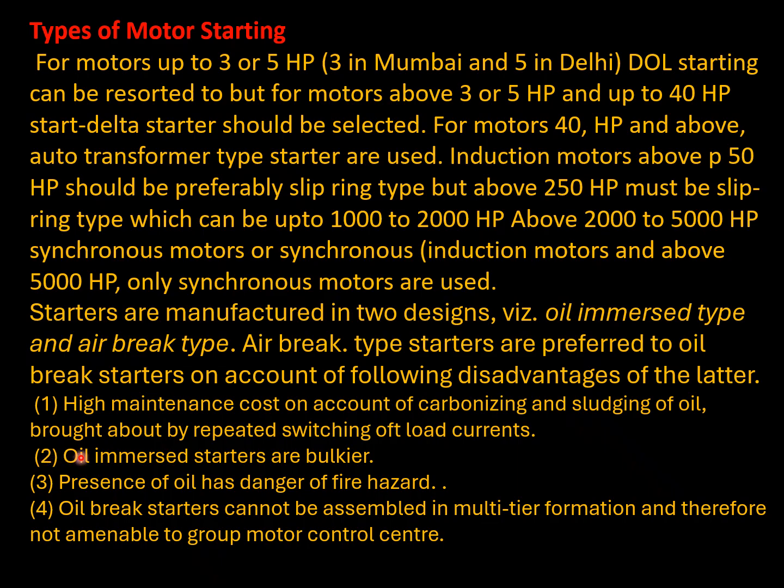Second, oil immersed starters are bulkier, heavier. Third, presence of the oil has danger of fire hazard. Fourth, oil break starters cannot be assembled in multi-tier formation and therefore not amenable to group motor control center.